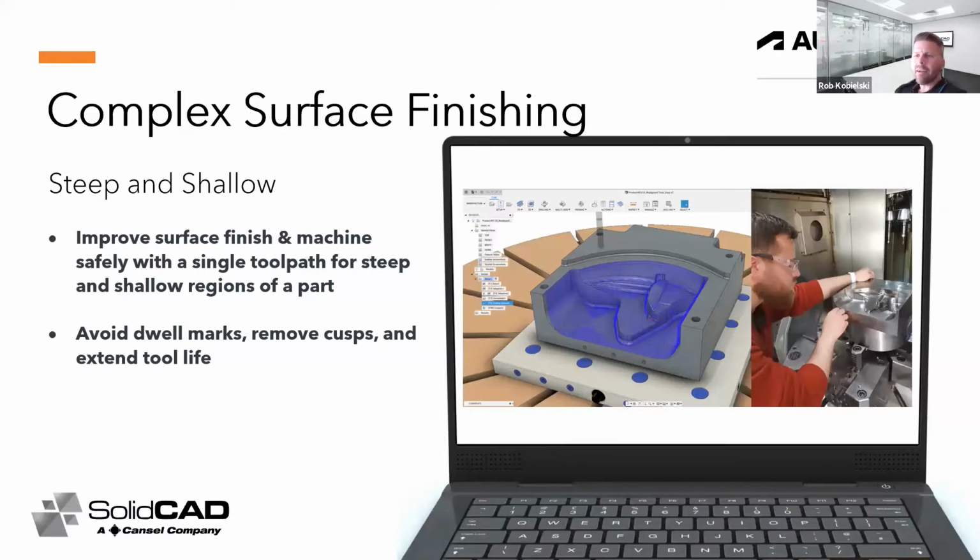Next, we're going to look at a toolpath strategy available in the manufacturing extension named Steep and Shallow. This versatile toolpath combines 2 toolpaths into one for optimal surface finish and reduced programming time. It applies one strategy to steep areas, much like a contour or Z-level toolpath, and it applies another one to the shallow areas, whether scallop or parallel, also known as raster.